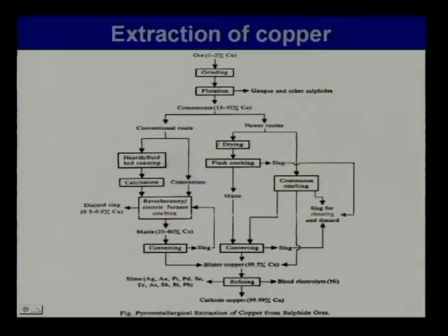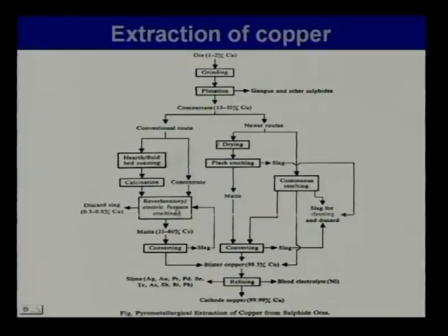So, all the oxygen has been eliminated from the system, and the slag that comes out has most of the iron slagged out, FeO with silica, limestone, quartz, etc. in a slag. It will also take out a small amount of copper, obviously that we cannot ensure. But basically oxygen is eliminated from the system, but what we get is a matte mixture of iron sulphide and copper sulphide.